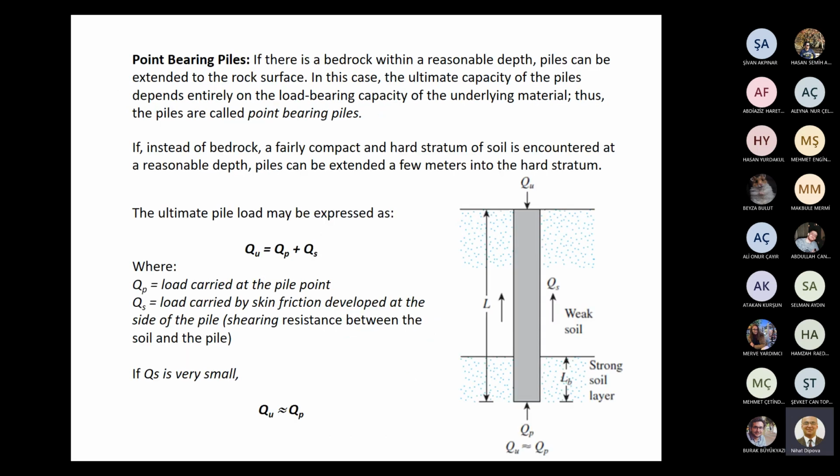Let us go into detail. Let us start with point-bearing piles. If there's a bedrock within a reasonable depth, piles can be extended to the rock surface. In this case, the ultimate capacity of the piles depends entirely on the load-bearing capacity of the underlying material.